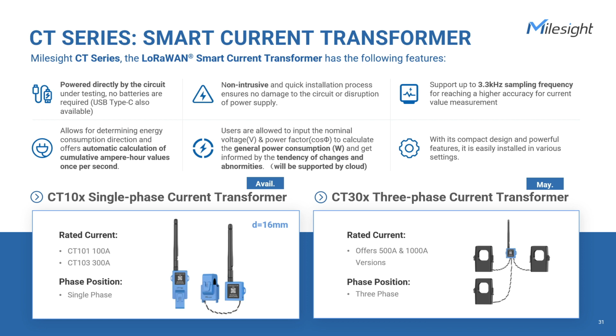If no current flows through the cable, the device can be powered through Type-C temporary charging, thanks to the embedded supercapacitor. When the current of the measured circuit reaches 0, the device can enter standby mode and remain operational for approximately 5 hours. Once the current is restored, the device can resume charging and normal operation.